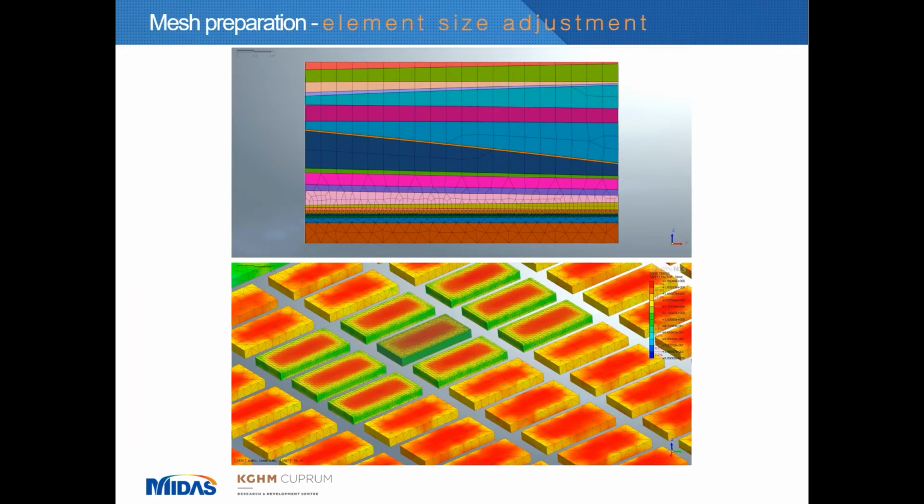And last, but of course not least, one of the key elements of the entire process of preparation of the numerical model is the generation of the mesh. For practical reasons, we cannot use the same mesh size for the entire model, because such an approach would involve the generation of several billions of finite elements, which would definitely be too much. It is necessary to increase the size of elements while keeping in mind the necessity to use a mesh dense enough to make calculation results reliable.